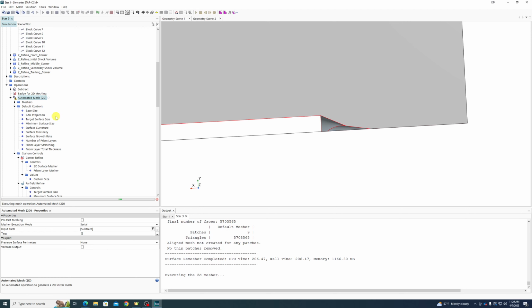There's advanced cases where if you're meshing multiple surfaces at once, it's a bit beyond the scope of this class, but there is a thing called concurrent meshing, which will do multiple independent surface meshes in parallel because they're not interacting. It'll do one surface mesh while it's working on another one, up to however many cores you have.